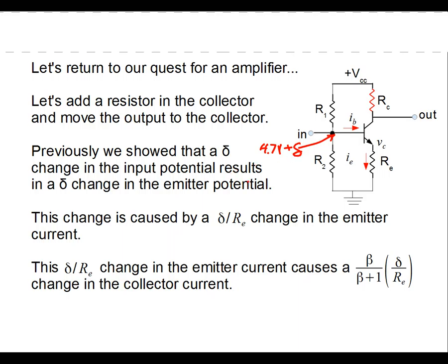Okay, so if I do that, what I notice over here is that the emitter will be 7/10 of a volt less. So it's 4 volts plus delta. Okay, we don't subtract delta. We're subtracting 7/10 of a volt from the base voltage, not from 4.7 and delta individually. So that's why we just have one case.